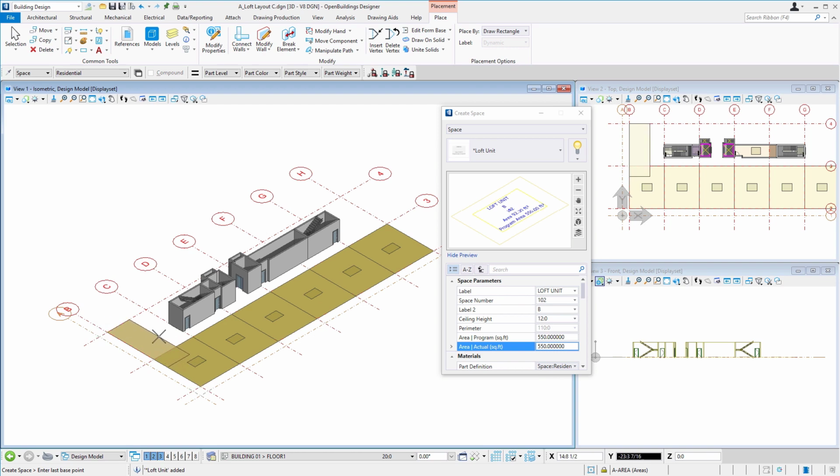Notice though that it's looking for a point along the x-axis. That's the way the rectangle is defined. So I can control that by rotating my AccuDraw compass so that I get the axis that I want to define. So there's a simple shortcut key in, which is RZ, and that will rotate your compass 90 degrees.